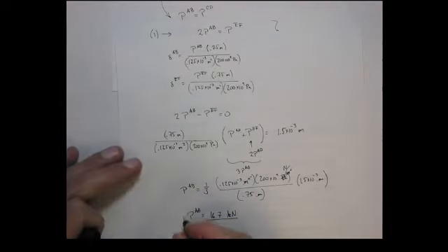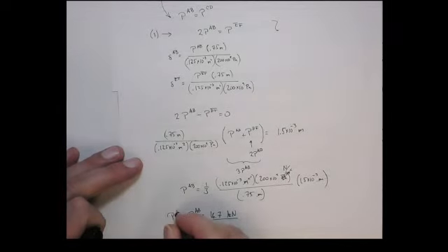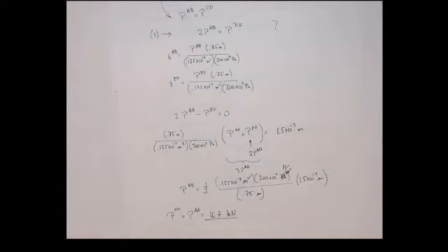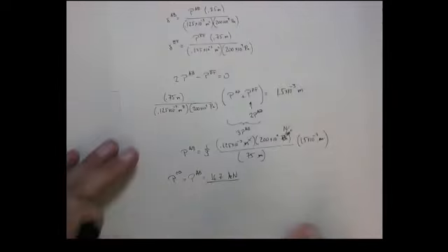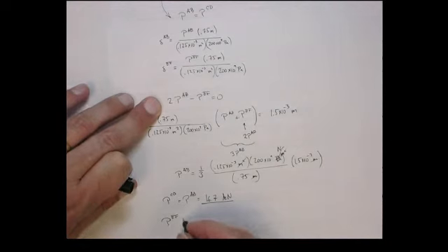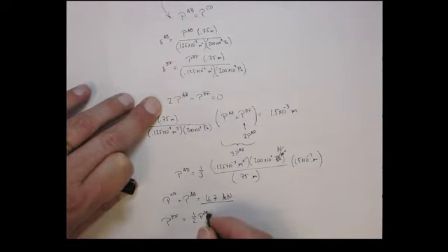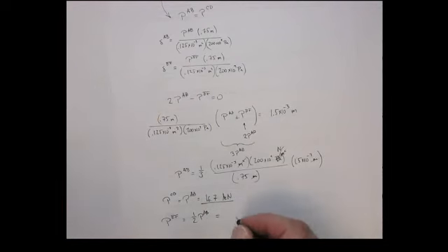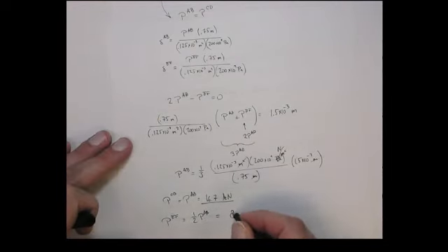And we know that's also going to be the force in CD. Now the force in EF, we can get from that. It's going to be equal to 1/2 the force in AB. And so that is just 8.35 kilonewtons. Okay?